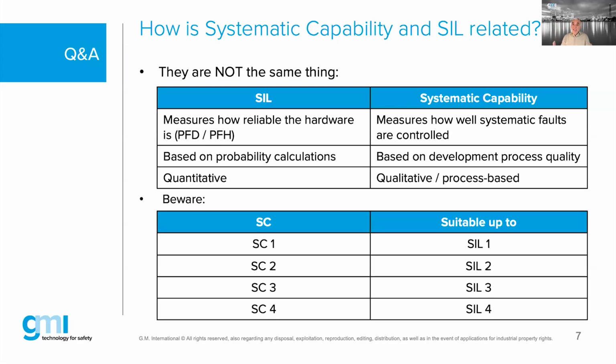And the bottom one, I swapped those tables. The left-hand side is now reflecting the systematic capability. And please remember this. When you can find evidence from the vendor on a certificate, report or datasheet, not on ChatGPT, that you have a systematic capability of 1 on that specific subsystem, make it easy and tell yourself you can only use that device for maximum SIL 1.